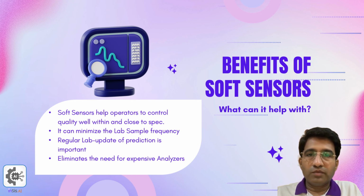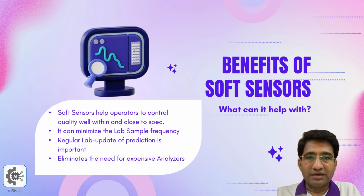So let's talk about the benefits. As a soft sensor provides the real-time quality information right in the DCS or PLC or SCADA, the operators can move the input parameters in order to control the quality right on the spec. And by doing so, they can also minimize the quality giveaway while ensuring product is within the specification.